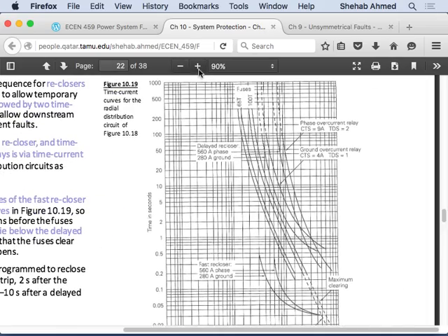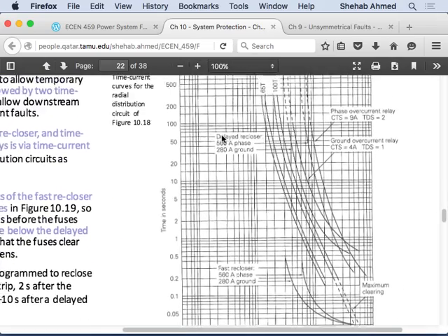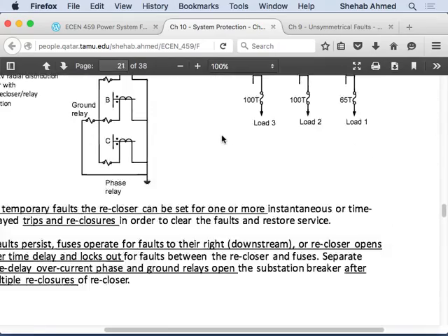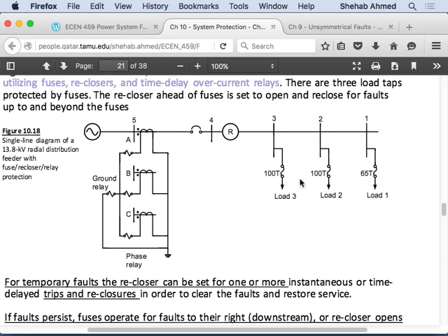For example, here, they show you fuses with breakers, and so they have a system here, composed of these, which are different houses, for example, and this is a recloser and this is a breaker. So they use 3 protection devices. They use some fuses here. They use a recloser, which is a device that opens and closes multiple times, and then it locks out at some point. And then they use a breaker. So you can have multiple kinds of protection devices. How do you want to coordinate these? You want to make sure that what?